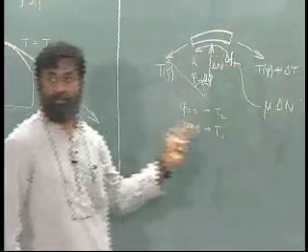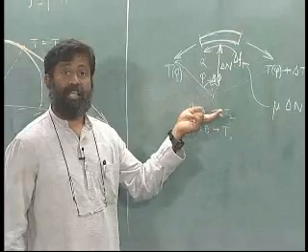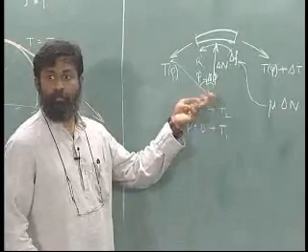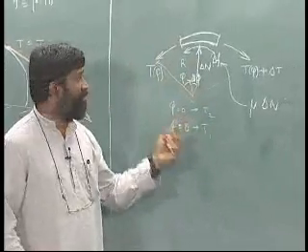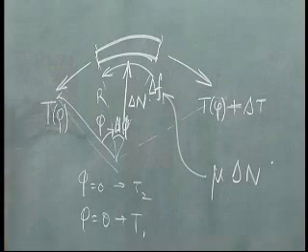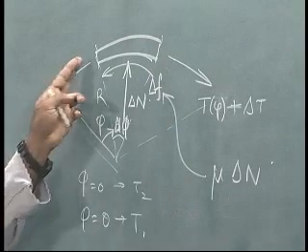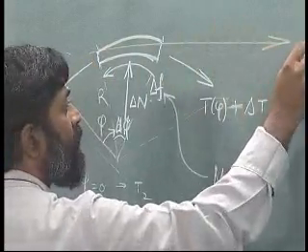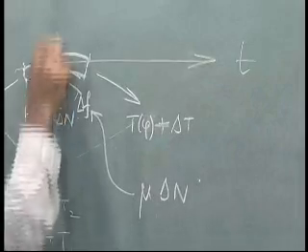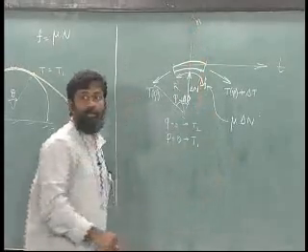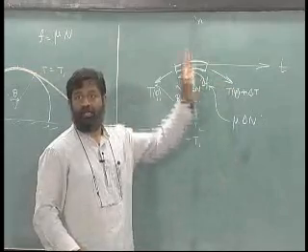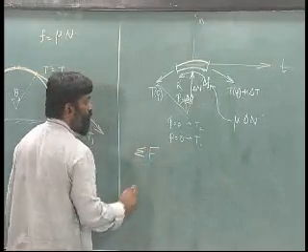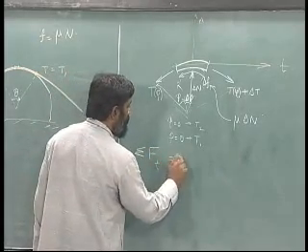Having drawn this, now I just have to apply the static equilibrium condition, because it is just an impending motion, in order to find the relationships between all these that you are seeing. Now, since this element is very small, I can take a tangential direction. Let me call this tangential direction t and the normal direction n, and take the equilibrium along t and along n. In other words, the total force along t is equal to 0 for this body.